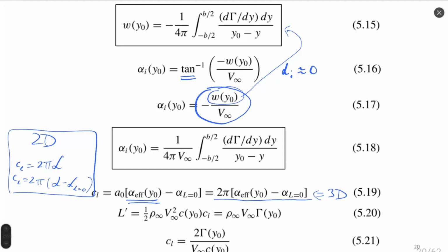Once you obtain lift coefficient in equation 19, you can use this coefficient to calculate total lift. As a classical definition from our previous discussion, lift would be proportional to dynamic pressure, chord size, multiplied by lift coefficient.